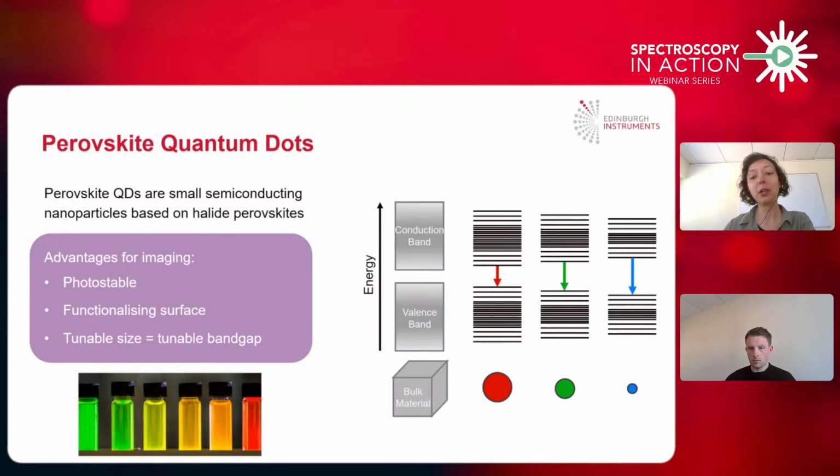I'm only going to talk about it very briefly, about quantum confinement. On the first column there, we have a bulk semiconductor. In a bulk semiconductor, there's a very large number of atoms, and the overlap of atomic orbitals creates a continuum which forms the valence and conduction bands. But when we reduce this semiconductor to a nanoscale size, the band gap between valence and conduction bands becomes wider as you make it smaller, and this is known as quantum confinement.